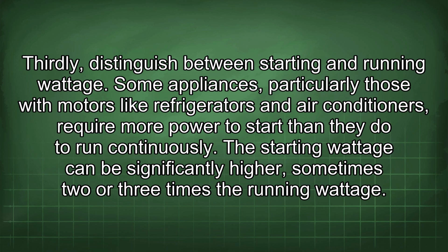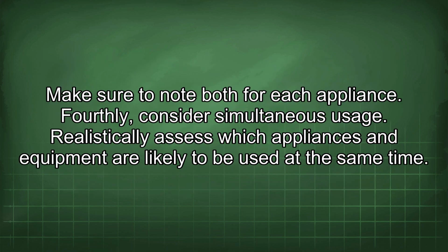Thirdly, distinguish between starting and running wattage. Some appliances, particularly those with motors like refrigerators and air conditioners, require more power to start than they do to run continuously. The starting wattage can be significantly higher, sometimes 2 or 3 times the running wattage. Make sure to note both for each appliance.